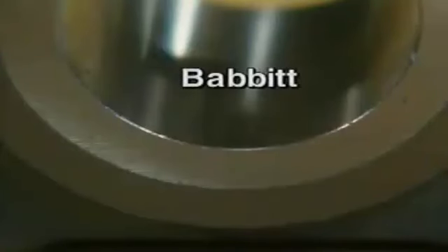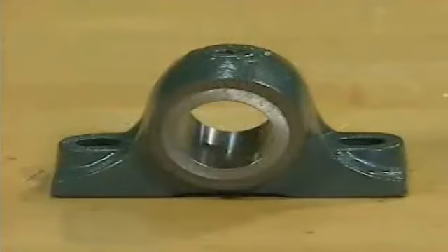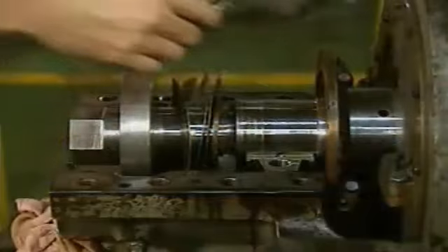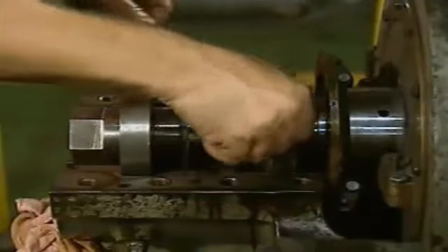The material that is most commonly used to make sliding surface bearings is babbitt. Babbitt is an alloy made of three metals: tin, antimony, and copper. The actual amount of each metal that is put into the material varies according to the way that the bearing is to be used. Babbitt is relatively soft, so it is always bonded to a shell that is made of a stronger metal, such as iron or steel, if it is intended to support a heavy load. Babbitt is a very useful bearing material because it has all of the properties that a bearing material should have.